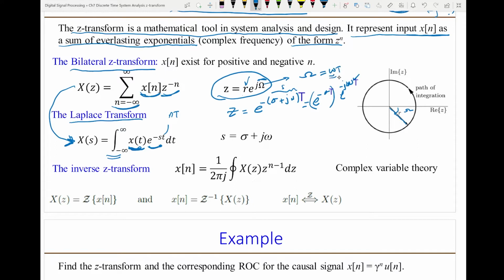So you multiply omega by the sampling interval, or it's the same as omega over fs, where fs is the sampling rate. So that is 2 pi f over fs. Now, because fs, the sampling rate, is twice the highest frequency in the signal, this is always going to be less than half. So half times 2 pi, that means omega will always be less than pi. The 2 will cancel here and you have pi. And that's the digital frequency. For sampling with no aliasing, the digital frequency omega is from 0 to pi. This is all possible omega.